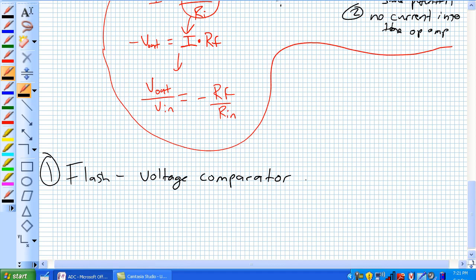It's the highest throughput. This is basically used for communication devices when you need to speak and convert and someone needs to hear you immediately. Think of your cell phone, radio, telephone communications like that. You want no delay between the conversion of an analog signal to a digital. The disadvantage of this guy, it's using lots of hardware for higher resolution. So let's write those down.